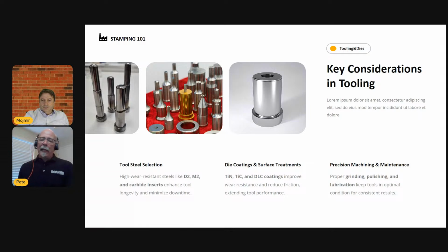And there's a variety of die coatings. TiN, TiCN, DLC coatings are just a few. There's aluminum carbonitride. There's all kinds of different types of die coatings. I suggest working with your tool steel supplier and your coating person when you're looking at coatings. So I will say this, and at the end, I'll show some slides I have to better illustrate this. I'm going to go back to deep drawing.